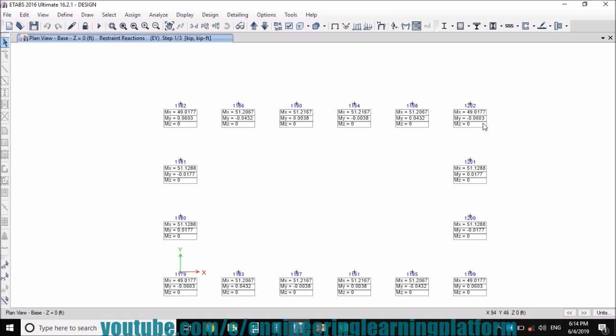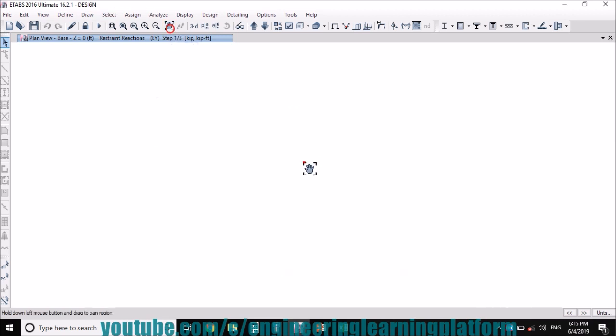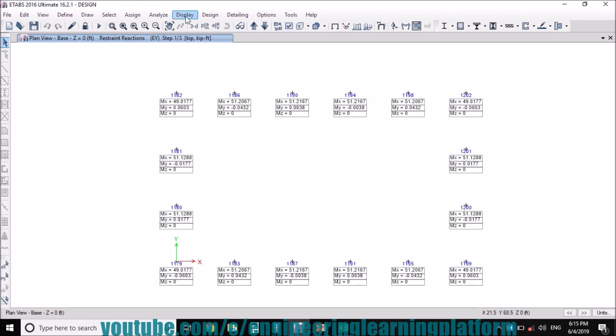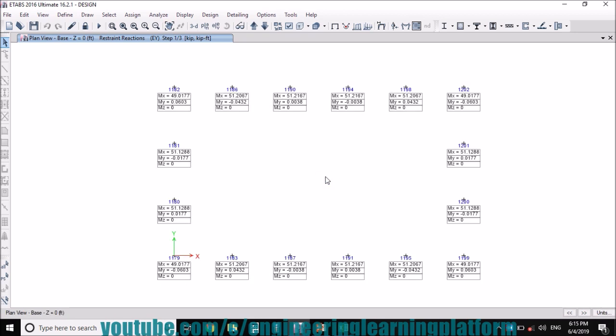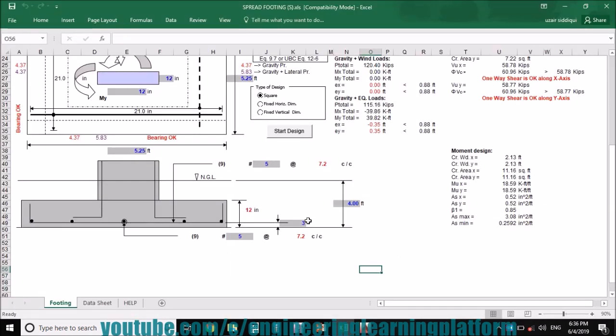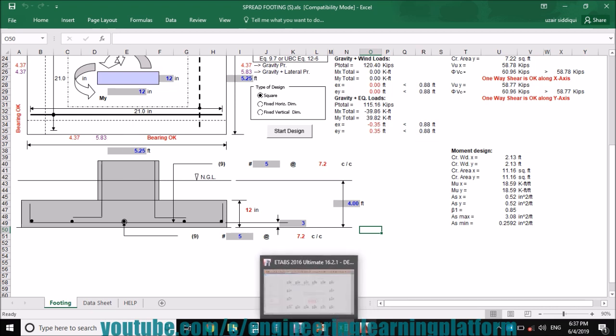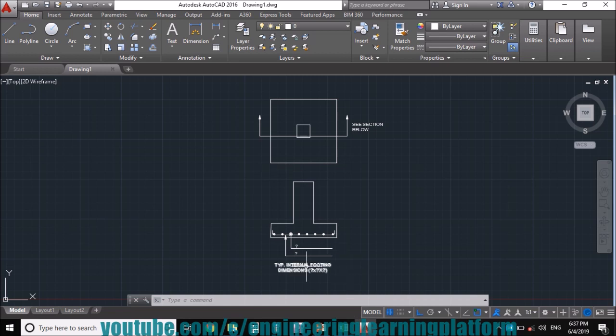Similarly, you can design the exterior footings by inverting the visibility option. Definitely it is very easy using this Excel sheet. You have to do nothing, just import the loads and specify the combinations based on the cases or the code you use. Since I use ACI and UBC 97, I have specified those.